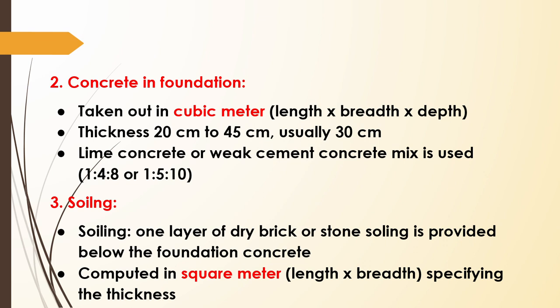Now after soiling, we will provide a concrete. So foundation is made by concrete. A base of the foundation is made by concrete. So we will place concrete over that. So that amount of concrete is calculated by cubic meter. That is length into breadth into depth. How much depth we are providing the concrete, how much length, and how much breadth.